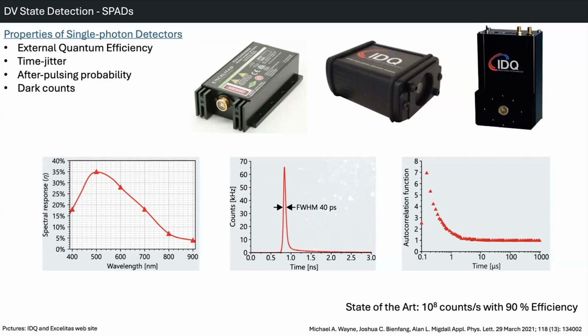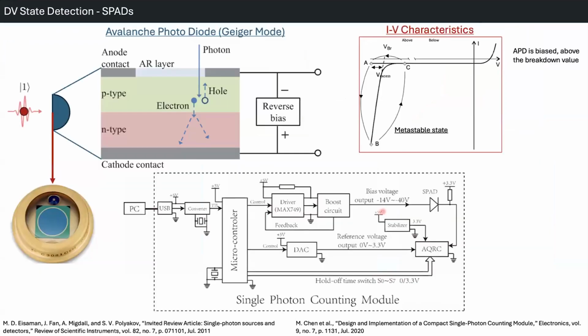So you need to quench the circuits with active or passive quenching circuits. Then it's what I showed you in the previous lecture. It's a little bit complicated device, but there are already two companies working on this in Turkey, producing these modules. They are just getting the diodes from very well-known semiconductor companies. Then they are producing these modules, which you can easily buy from the internet. Then you are getting a single photon detector.